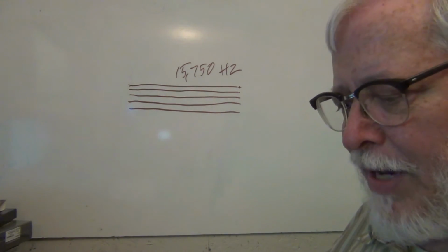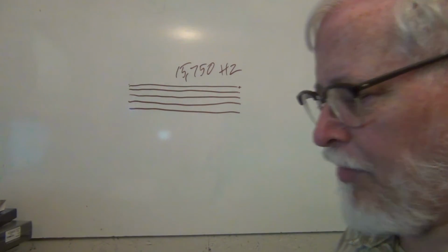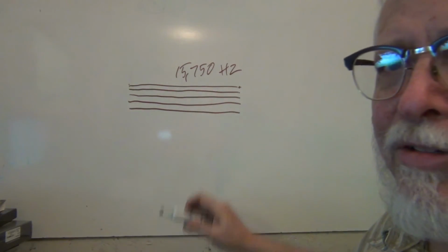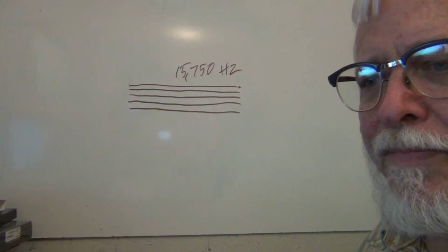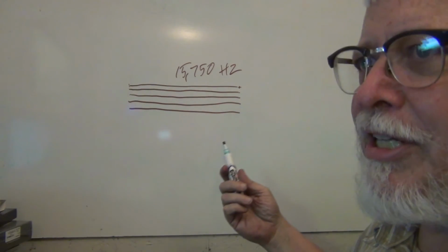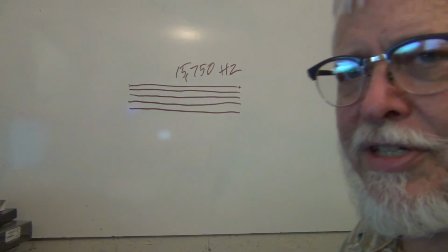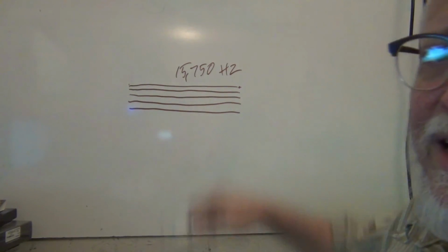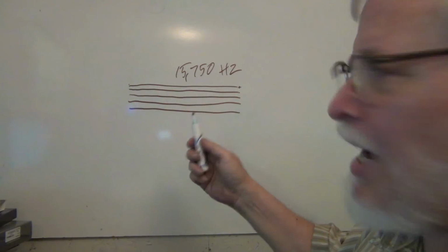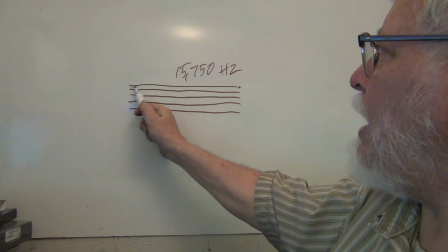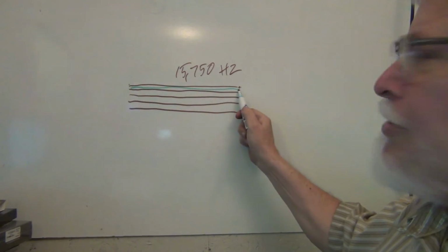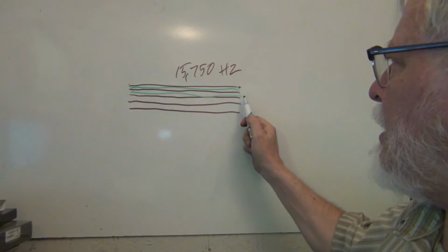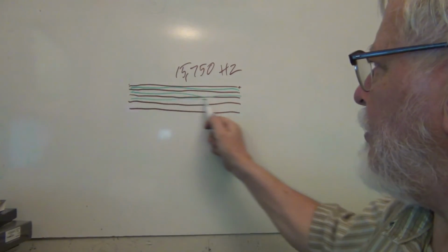Now the magic thing about video is that that's called a field. When it gets to the bottom of the frame, in regular NTSC video, it's done 262.5 lines. And so then the next time up, because of a trick in timing they do, it actually comes back and draws another line in between the first one and the second one, and then between the second one and the third one.